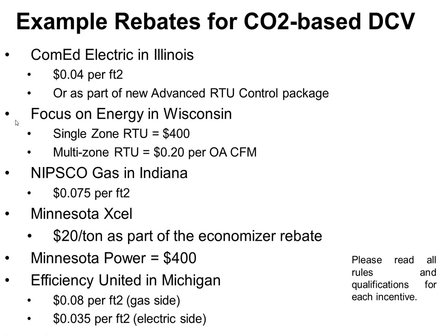You need to put a CO2 sensor with the stat, right? That is the absolute best and most surefire way to do it. There is one controls manufacturer that does it differently. There is a portion in ASHRAE 62.1 called equation 6.1, and that allows you to do the multi-zone calculations, and you can pick critical zones like conference rooms and put your sensors there, and then use the calculations to kind of predict everything else that's going to happen.